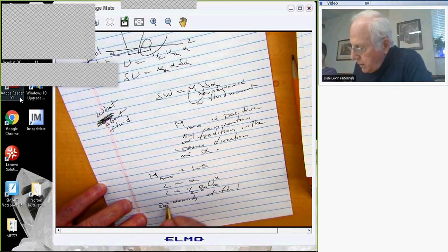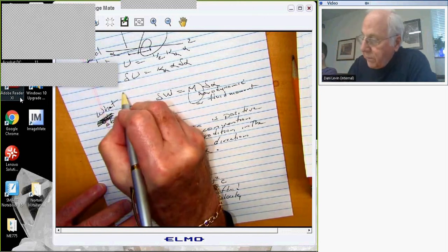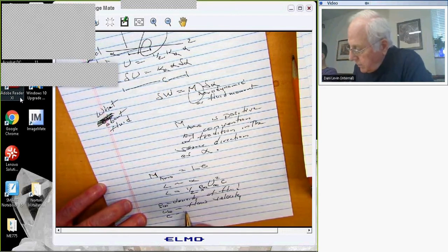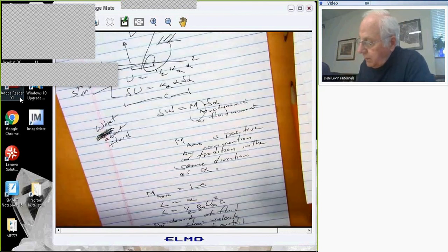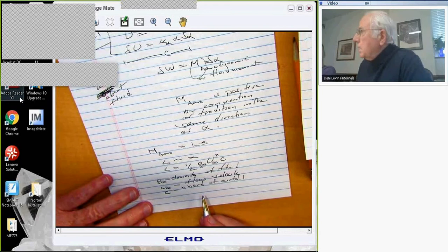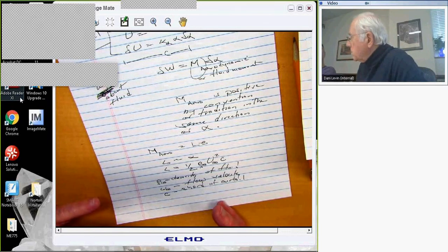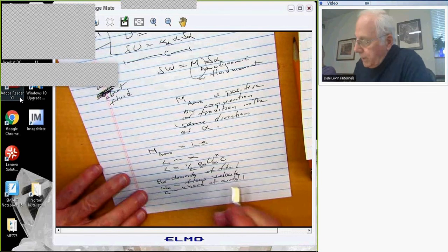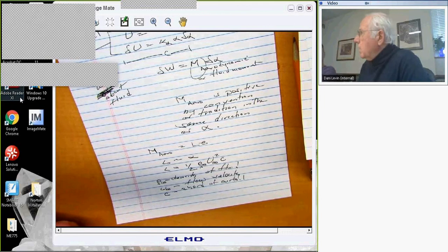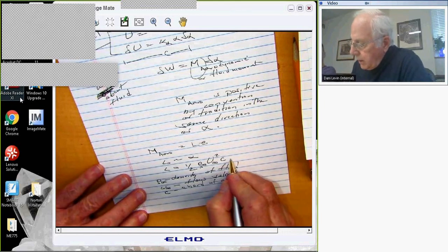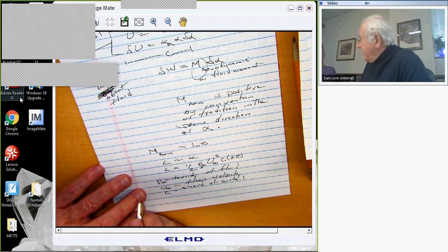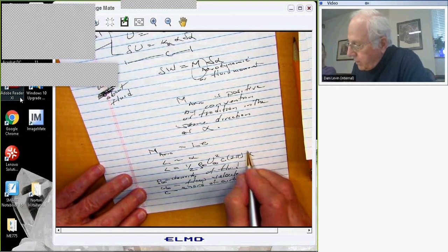I'll put a sub-infinity on these so we'll know we're talking about fluid. This is flow velocity. Times c, which is the chord of this airfoil, times some constant. And the constant, you could argue, has to be of order 1, although I'm going to press the definition of order 1 a little bit here. It turns out in low speed flow, low speed meaning I'm well below the speed of sound, it turns out to be a number like 2 pi. Okay. And then, of course, most importantly, it's proportional to alpha.